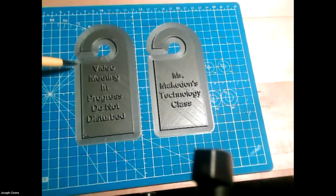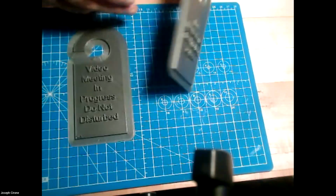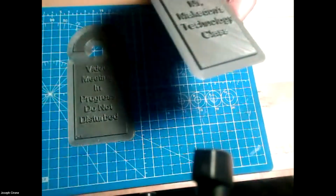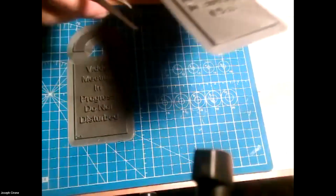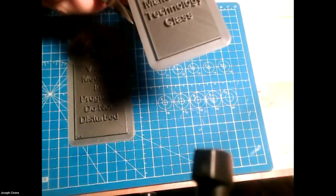Okay, so as we look at our project, here we have 2 of the projects that have been printed. You can see that we have this build plate adhesion on it, and this needs to be removed. We'll remove that with either pliers, and you can pull that off, or you can use a clipper to clip that.